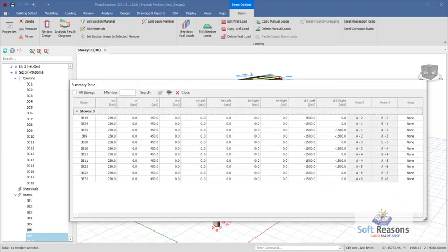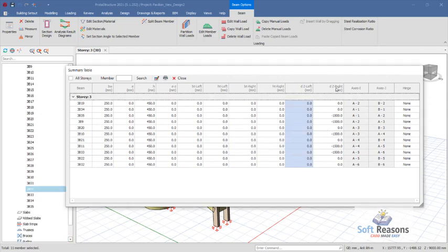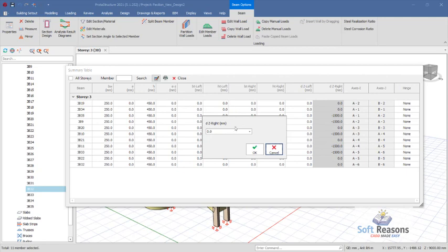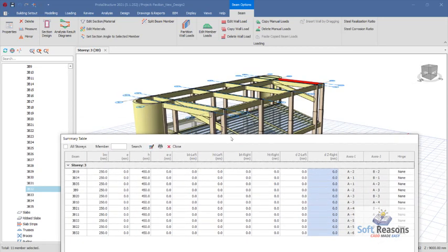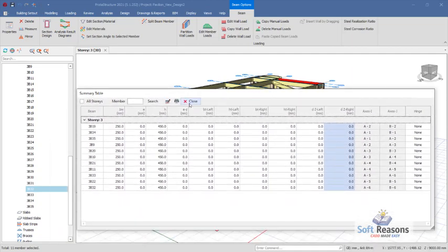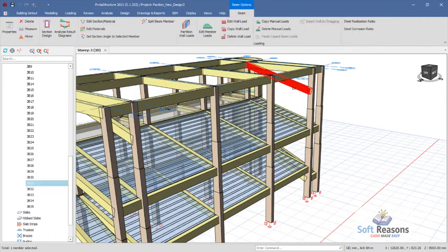So in this property dialog, let's check the DZ. Okay, its constraint of 1500 is affecting the beams. Change it to 0 right there to have the beams at the normal level. Also change this to 0 right there, just like this. Okay, I believe everything has moved to normal level. Click on the close options. Then these other two beams we have in there, get rid of that by deleting it, just like this.